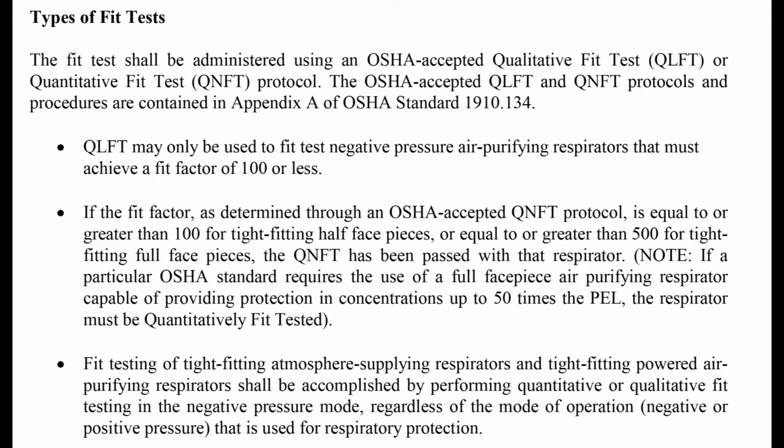Types of fit test. The fit test shall be administered using an OSHA-accepted qualitative fit test (QLFT) or quantitative fit test (QNFT) protocol. The OSHA-accepted QLFT and QNFT protocols and procedures are contained in Appendix A of OSHA Standard 1910.134. QLFT may be used only to fit negative pressure air purifying respirators that must achieve a fit factor of 100 or less. If the fit factor as determined through an OSHA-accepted QNFT protocol is equal to or greater than 100 for tight-fitting half facepieces, or equal to or greater than 500 for tight-fitting full facepieces, the QNFT has been passed with that respirator. Note, if a particular OSHA standard requires the use of a full facepiece air purifying respirator capable of providing protection in concentrations of up to 50 times PEL, the respirator must be quantitatively fit tested.